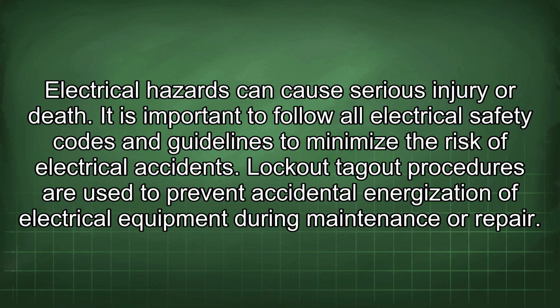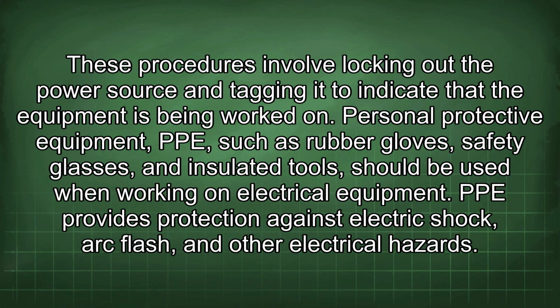Lockout-tagout procedures are used to prevent accidental energization of electrical equipment during maintenance or repair. These procedures involve locking out the power source and tagging it to indicate that the equipment is being worked on.